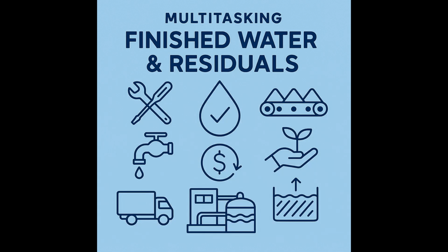Do these last stages generate much waste? Not continuously, no. Very minimal in normal operation. You might have occasional tank drain downs for cleaning or water flushed from the distribution mains. That water needs to be dechlorinated before it's discharged, usually to the storm drain or sanitary sewer. And again, empty chemical containers from disinfection.